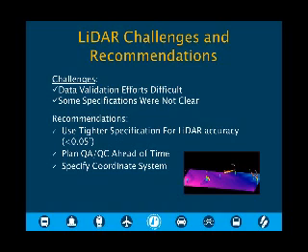And then we got all of the LiDAR information because we got the imagery in UTM coordinates. Minnesota uses a county coordinate system for all of our survey work. So we had a challenge getting it out of the UTM datum into our county coordinate system so that we could actually go and check this. That's one of the things in the spec that we need to do and specify. And we also recently purchased MnDOT's software. We feel this is going to help us with our future QA/QC products.